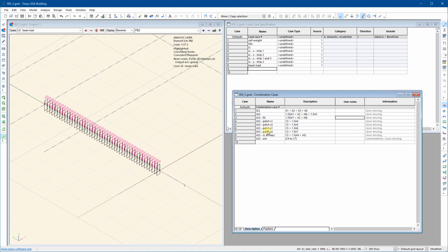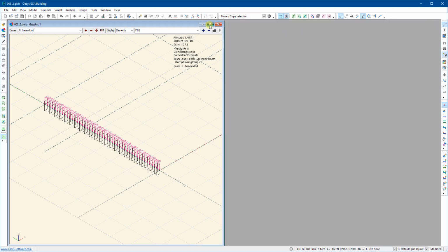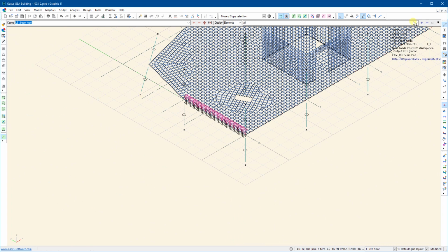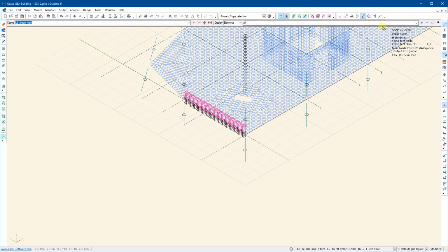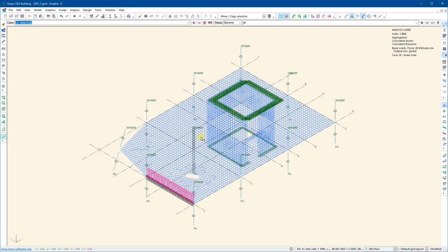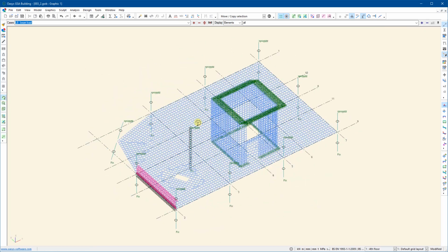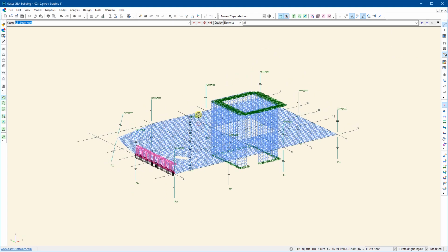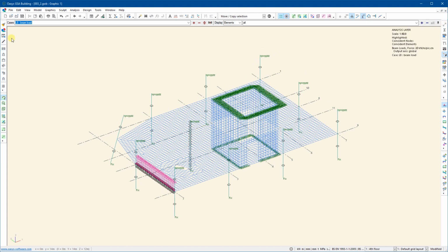So I've accounted for the beam load, so we should see that when we see the results. So I'll close all of this, go back to the floor plate model. I'll turn off the various annotations. Let's make it full screen. I'll only show the grid lines, again just for ease. I'll check my restraints so it's all fixed. So then everything now looks ready to go. So I'll save it again. What I'll do is I'll analyze this.